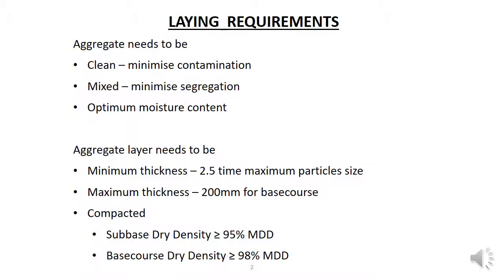Contamination can result from dust blowing into the mix or from stockpiling the aggregate in exposed positions for extended periods of time. Therefore, it is best to run the aggregate onto the road when it is delivered. This also avoids double handling the aggregate, which can cause segregation and adds time and cost to the laying operation.